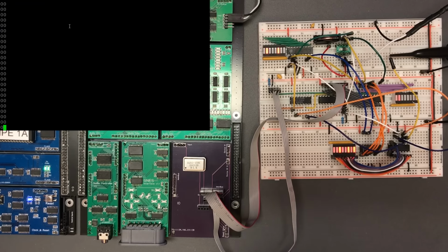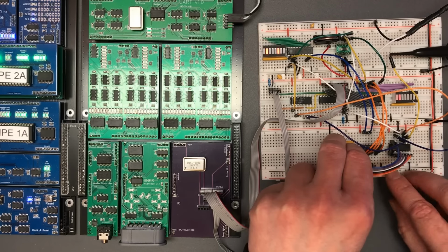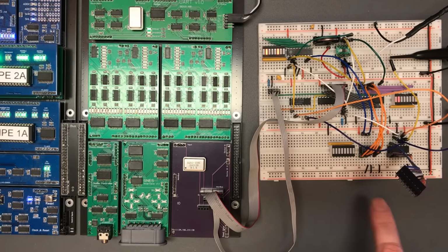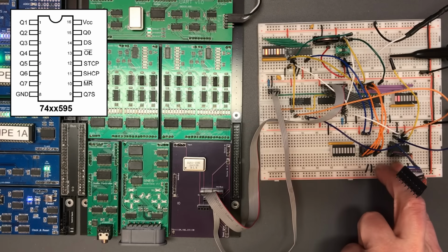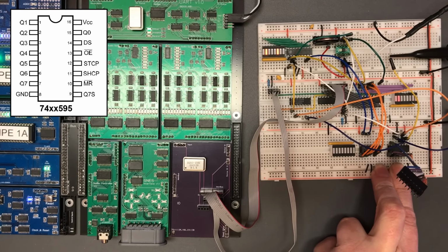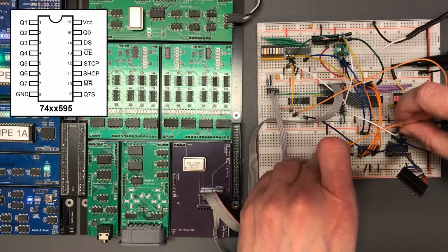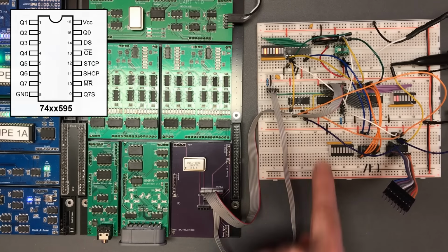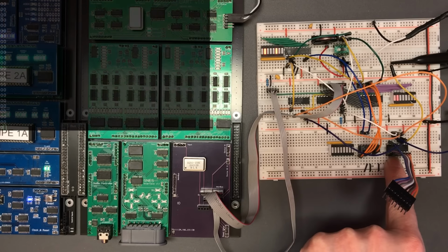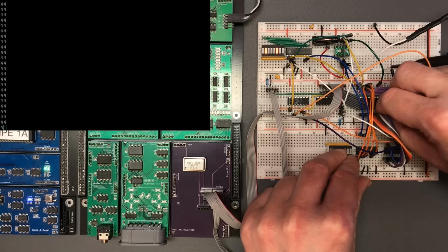Of course, we're getting nothing but zeros. So I've effectively disconnected this latch chip outright. But of course, the shift register's got a tri-state latch in it already. Now this is the output enable. Let's instead take that from the read line. This latch chip's doing nothing. This is doing all the work. Do need to connect it to the bus.